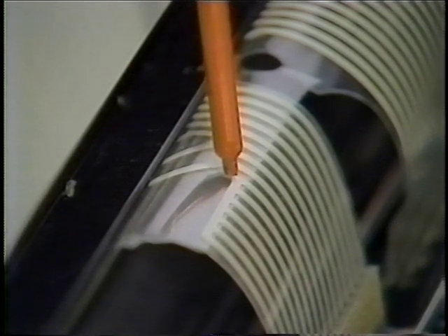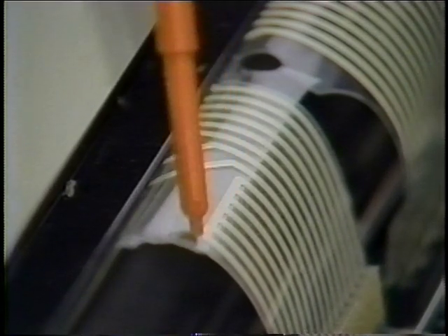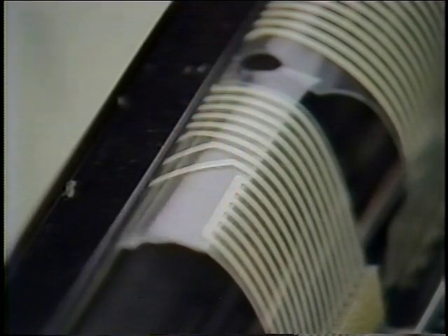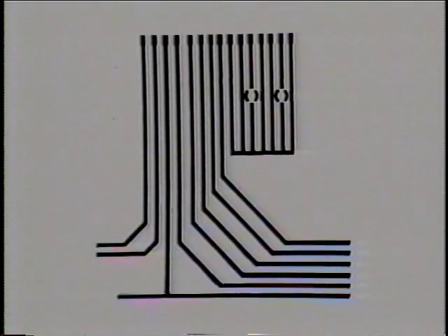The function board supplies 5 volts DC to pin 9 of the J2F connector and looks for the presence of 5 volts DC on pins 10 through 15. By changing the combination of pins on which the function board finds 5 volts DC, the keyboard ID is changed. This is accomplished by opening some of the ID lines by punching a hole in them. The ID holes are punched during manufacturing.